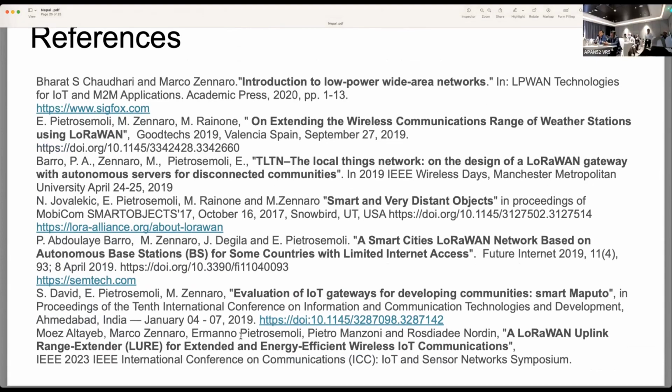So the LoRaWAN, that works as a multicast, right? I mean to say that it's not a point-to-point. Not really point-to-point, because it's always a sort of broadcasting, okay? So a gateway is able to receive from many end nodes, even the ones that do not belong to the same organization.